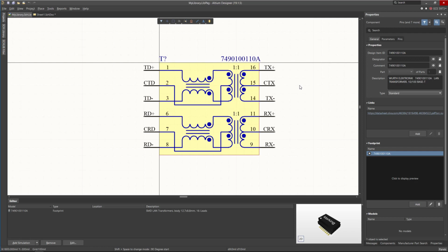Also, there is another point we need to focus on in the layout for the PCB footprint components. Now, where else can I access the editor properties as well? Remember, there are toolbars in here you can show. Altium Designer by default hides all these toolbars because you have shortcuts, you have the dynamic properties panel.